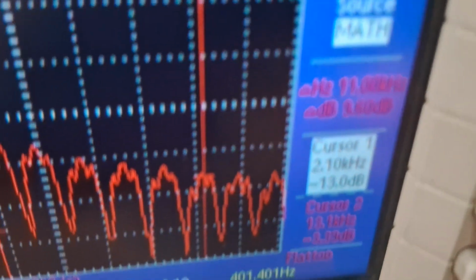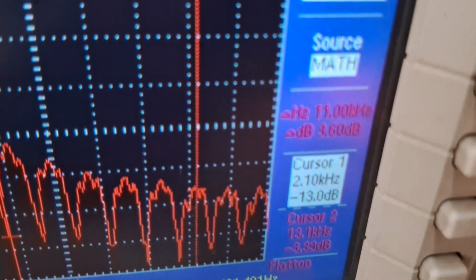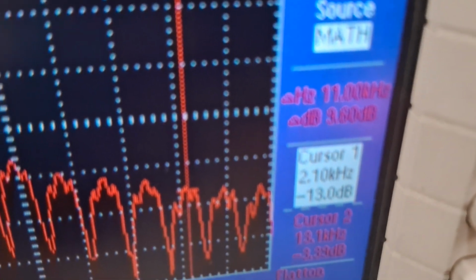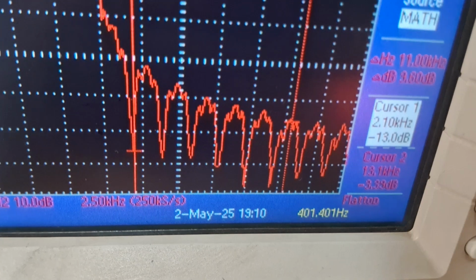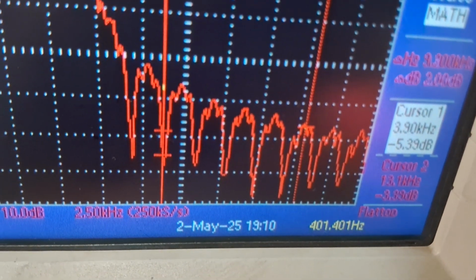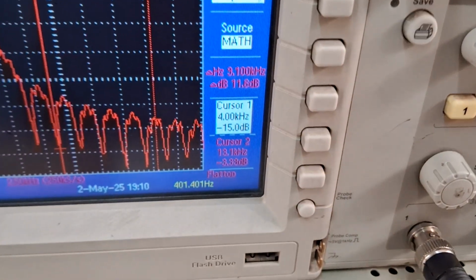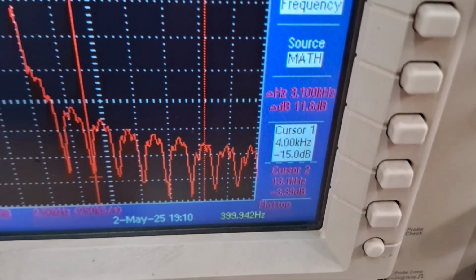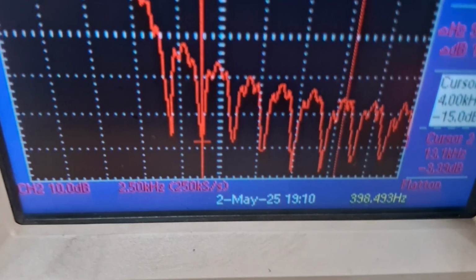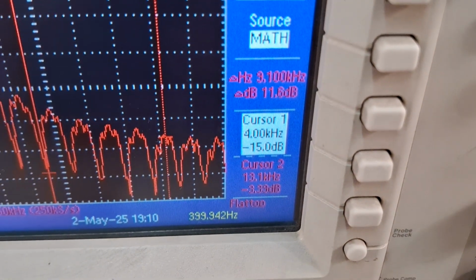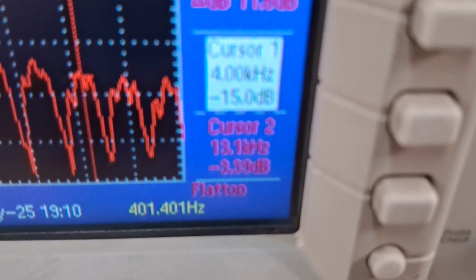What we'll see is the frequency of 1 upon tau. What is the frequency corresponding to it? You can see that it is 2 kilohertz. Can you see here? So it's 2 kilohertz corresponding to it. Then I'll move the cursor to the next position. It is going to be 4 kilohertz, the next position of the signal. So it's approximately how much? It is approximately 3.1 something. So it's corresponding. You have to place the cursor exactly at the position. If there is a manual error, the error may be in the reading itself. So it's 4 kilohertz, that is the cursor position is nothing but 4 kilohertz.